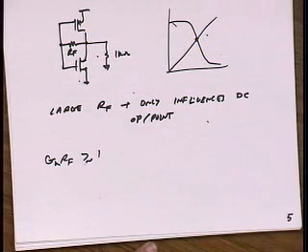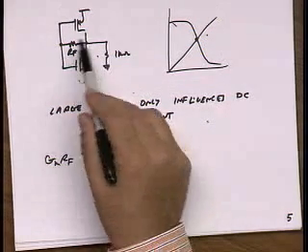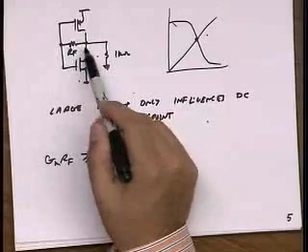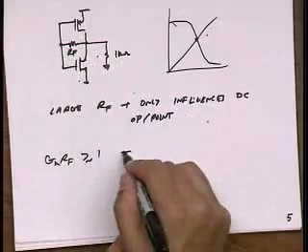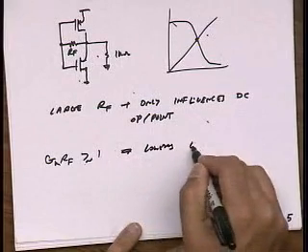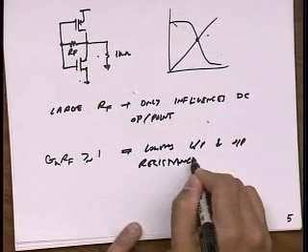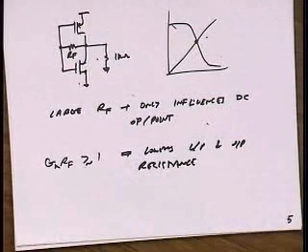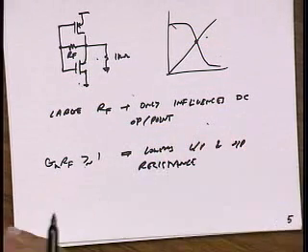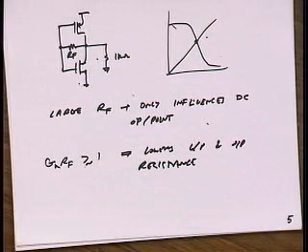Debo? You get a lower output impedance also. Yeah, so if you really let the shunt feedback do what it does best, it can lower the input and output resistance, right? So this lowers input and output resistance. One is good, one is bad, right? Lowering the output resistance is helpful. Lowering the input resistance is not good, because now it becomes more difficult to drive this circuit. It tends to load the stage that's driving it. But it's actually a pretty good solution.